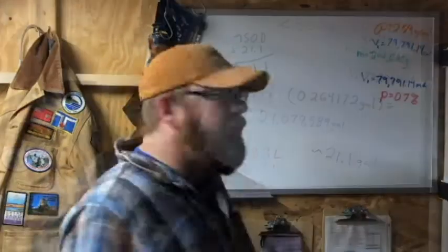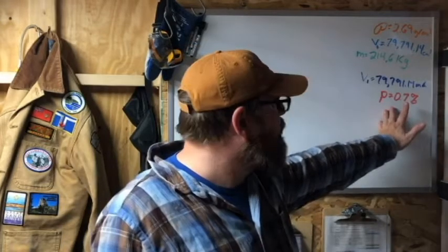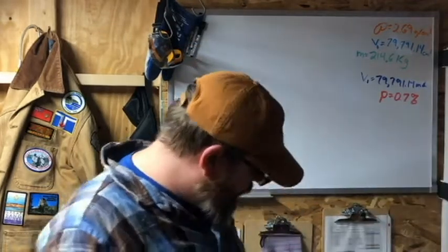We're almost done. So our third and final question that we've taken from our story problem, we want to know if the porosity will significantly lighten the weight or reduce the mass of our sandstone block. And that was given to us in that USGS publication from the Dolomitic Mount Simon sandstone at 0.7%. Now, I'm just going to use the P for that.